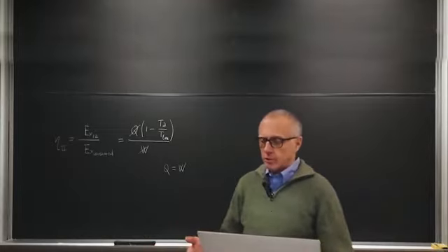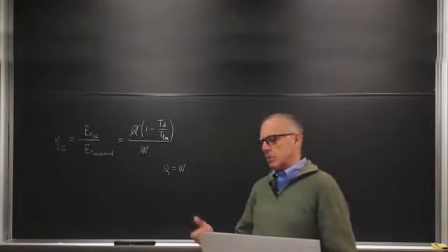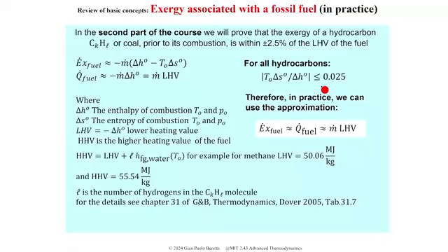So if you accept that kind of approximation, and typically in exergy computations you can afford that kind of precision, you can simply neglect this part, and so the exergy and the heating value are approximately equal. So you can say that the exergy of the fuel is approximately equal to the heating value of the fuel, which is in turn approximately equal to the lower heating value.